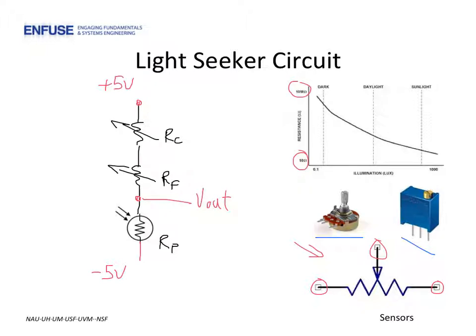And again, we could connect that to an op-amp comparator to give us an analog system, or we could set up the voltages at the top of the series to 5 volts here, or just make this ground, and then take this output and move it to a digital analog converter, and again use a microcontroller to operate the circuit.